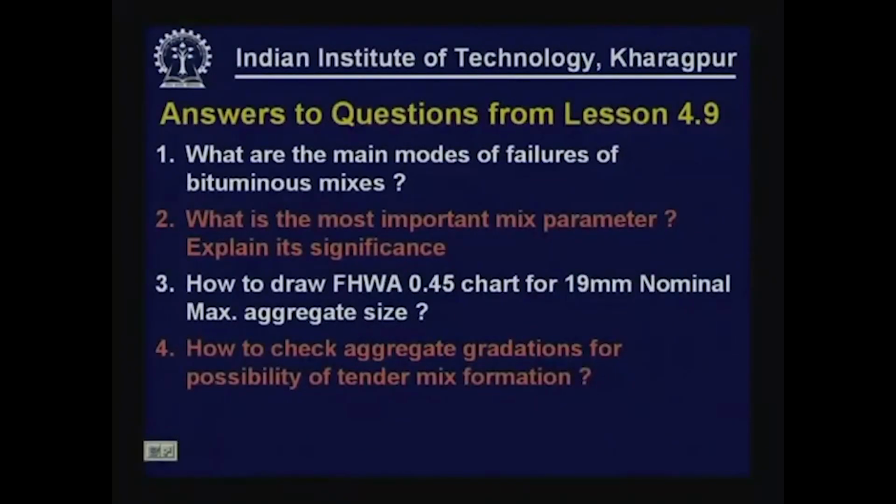is a major problem. Also, rutting is one of the major failures of many bituminous pavements in India because of the high temperature conditions. So, rutting or permanent deformation occurs mostly in bituminous mixes if they are thick at high temperatures, or it can of course also occur in other layers starting from subgrade, subbase, base, which then gets reflected onto the surface.